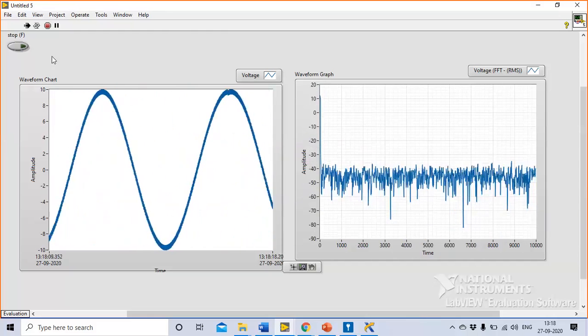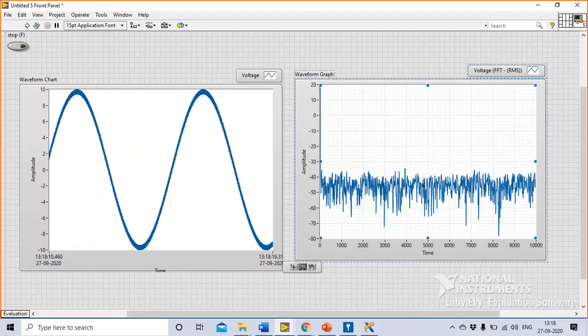I had used the same graph which had showed the data of the waveform earlier. I can always rename it as frequency. The x-axis is actually frequency. Okay, sorry, I thought it would come automatically in the graph. No, you have to select it, sir. So you can name it frequency. Now you can clearly see that we had acquired 20,000 samples, and it is showing the spectral analysis up to 10 kilohertz frequency. Nyquist. I'm sorry, actually I did not mention it here. So thank you for bringing it up, sir.